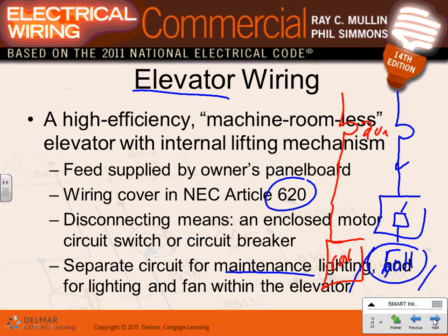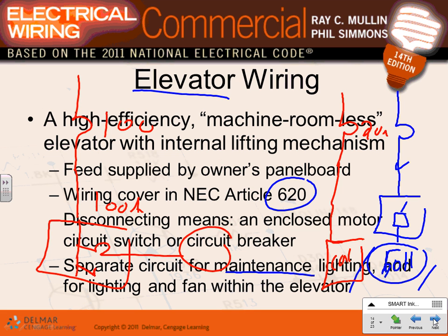Any comments, any questions? So most of the time, Jeff, if we have an elevator, like we haven't ever done with it, we take a feeder. Typically, they take a feeder, say 100 amp, to a panel. This is a 100 amp panel. And from this, you feed your elevator, and you feed a bunch of loads related to the elevator. And this will be right in the room, or the elevator room, dedicated for a small panel for the elevator. Very commonly used. Any comments, guys, about the elevator?